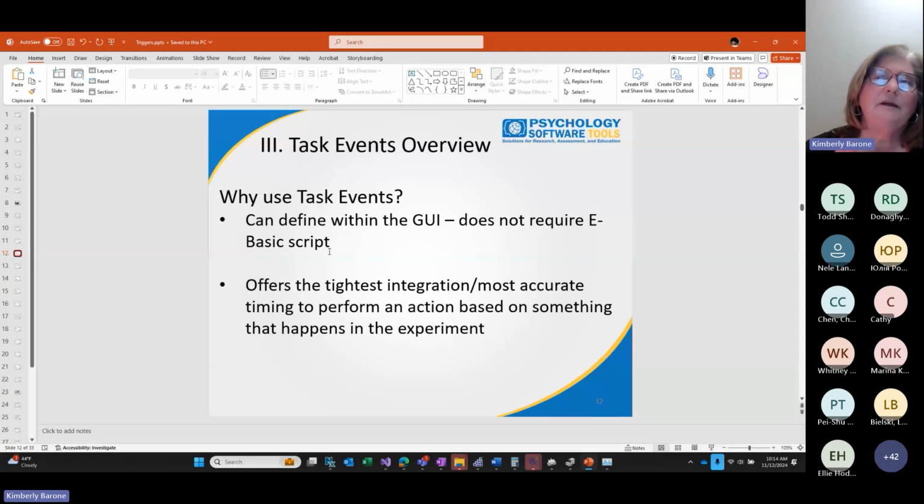Now, the difference we're talking about here for many, many people will be negligible. Task events are typically executed in a sub-millisecond to 1 to 2 millisecond time period. They're very, very quick. A non-task event may be executing within 2 to 3 to 4 milliseconds. So there's often not going to be a big difference, but it still is the best option that we can offer. So we strongly encourage everybody to migrate to using task events versus handling it in script.